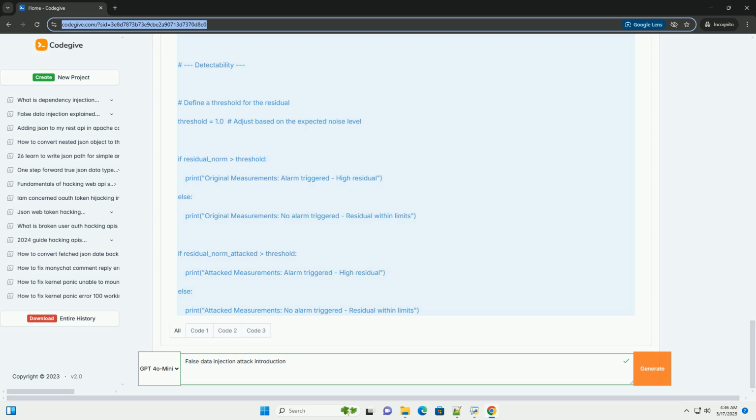The attacker needs to know the measurement matrix H, which describes the system's topology and sensor locations. This is often the most challenging part, requiring reconnaissance and potentially compromising the system to access configuration data. An attacker might also try to learn the topology through observing the system's behavior over time. 2. Select target state variables: the attacker chooses which state variables, x, to manipulate and by how much. This defines the vector c, which represents the desired change in the state estimate.